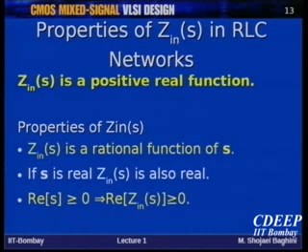If somehow I can convert the problem of realizing a transfer function to realizing an input impedance, then the problem of design is solved, right? So I can just realize the input impedance. Then the filter design problem is done.